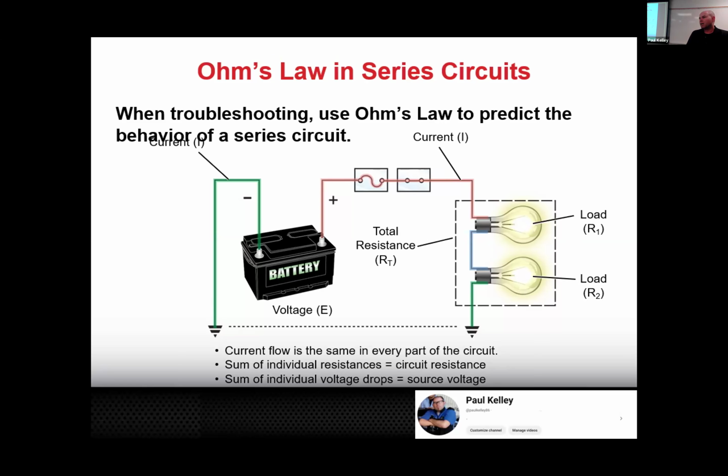And it does fix it a lot of times because the main failure point's in the filament. But as a professional, if they're bringing it to you and they're going to pay your diagnostic time, they probably already tried to throw bulbs in there. So you can look at the bulb and see if the filament's good, but on new stuff, it's an LED, you can't see. You look at it and you're like, is the LED good? I don't know. There's nothing to see. So what we'd probably really do is analyze the circuit and be like, do I think I have two bad LEDs? Or might I have a bad switch?